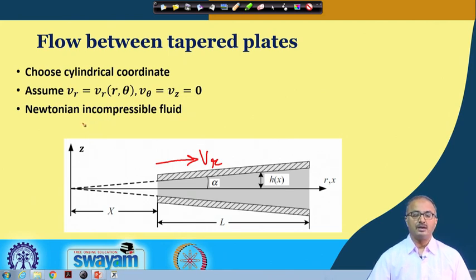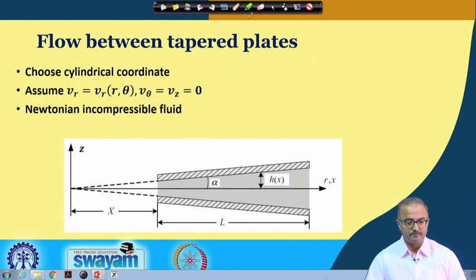That means we are assuming that the density is remaining constant, or also we make one assumption because nothing is given in the particular problem. If it is a gas, you may take the viscosity to be a function of the temperature, or for liquid, for some small range of temperature, you may consider the viscosity to be a constant. But these are not very restrictive assumptions. So let us now go further.